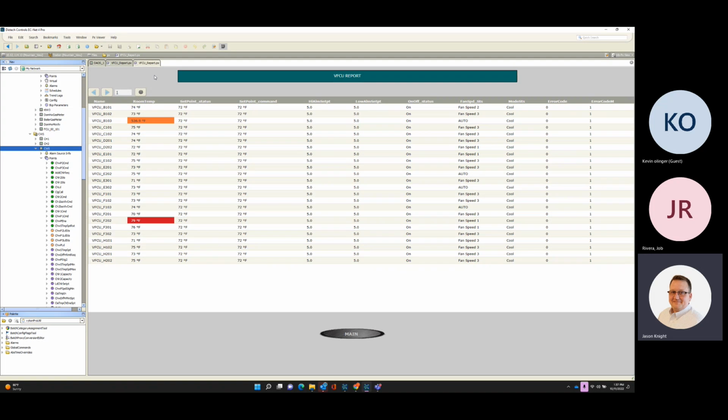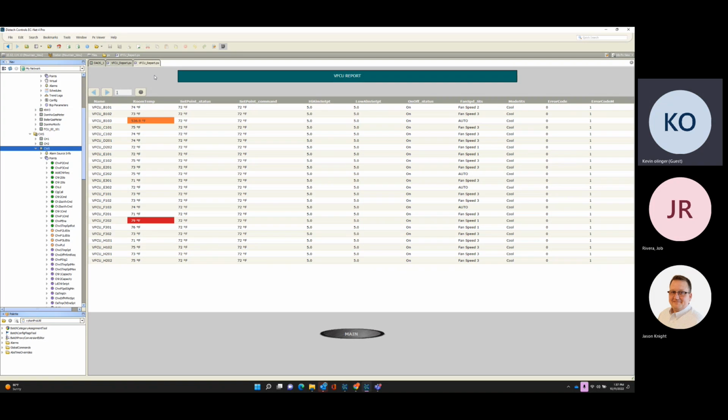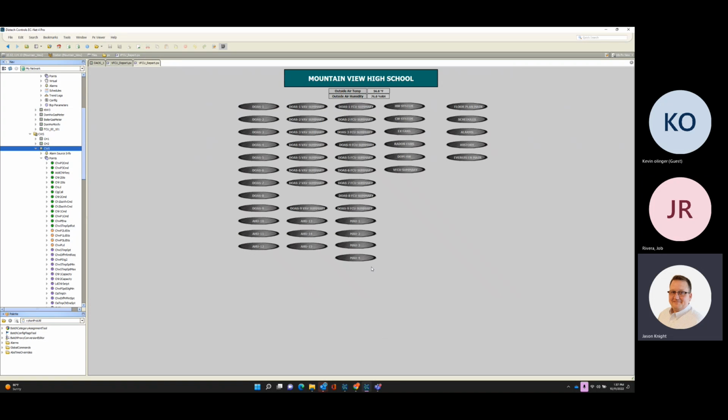If we run sector H at 6 pounds of differential chill water pressure, you'll be lucky to make 68-degree discharge air when you've got a 44-degree loop going. So we're still trying to finesse that, get that figured out, and see what they want to do about the pressures, and maybe they're going to add a valve or two, or who knows. So we're waiting to hear back on that. But the system works; it's stable. It just has to run just about wide open just to maintain enough flow. Yeah, pretty much.